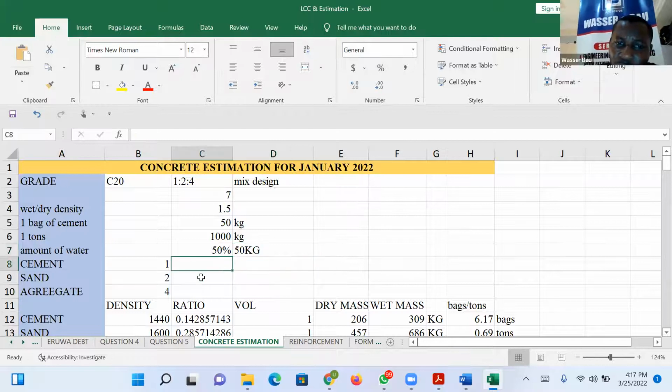Okay, take notes. And that reminds me, also know how to use local parameters, local measurement tools. If they're using cement buckets, 1 bag of cement will give you 2 cement buckets. But if you're using those old head pans, it will give you 2.5. So at the moment, treat 1 bag of cement as 2 buckets. So that when they are bringing 2 buckets, you know they're going to bring you 4 buckets of sand and then 8 buckets of stone to give you 1:2:4.